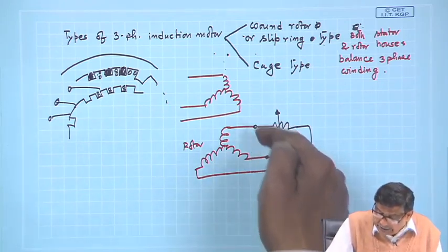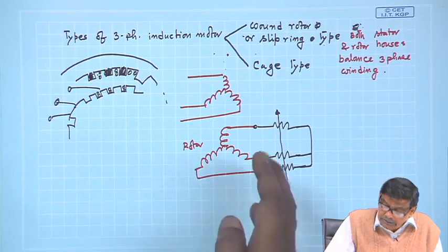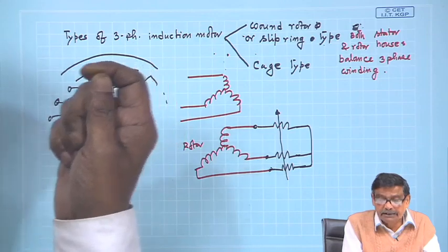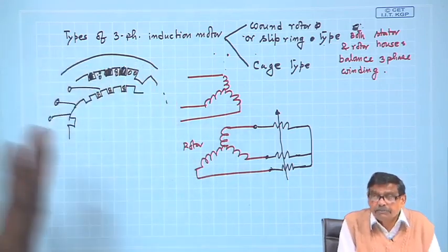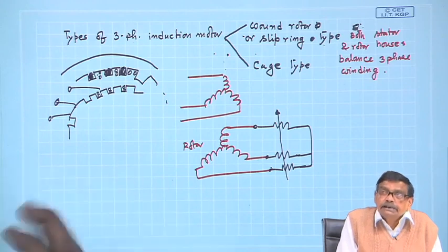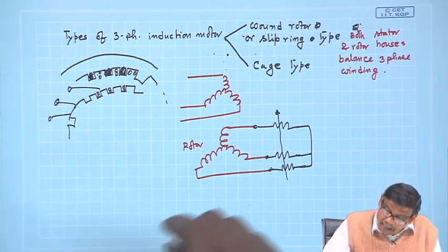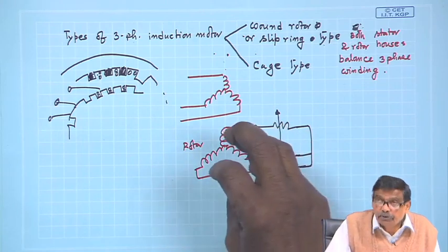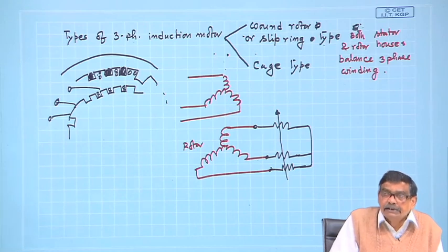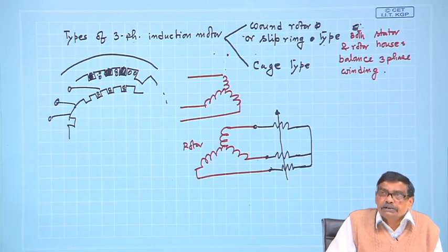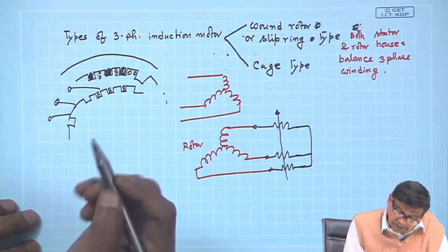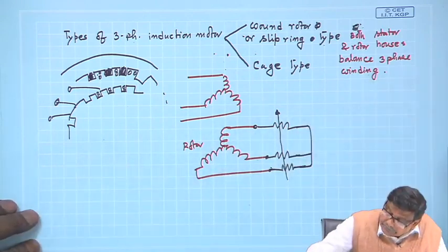Therefore, to access the rotor terminals properly, it cannot be like this, that rotor terminals are there and I will connect resistance. There must be some intermediary things which will make these 3 terminals, which will be rotating, appear stationary to the user of the motor, so that he can connect the resistance comfortably. Okay. So, how can this be done? It can be done very nicely like this.